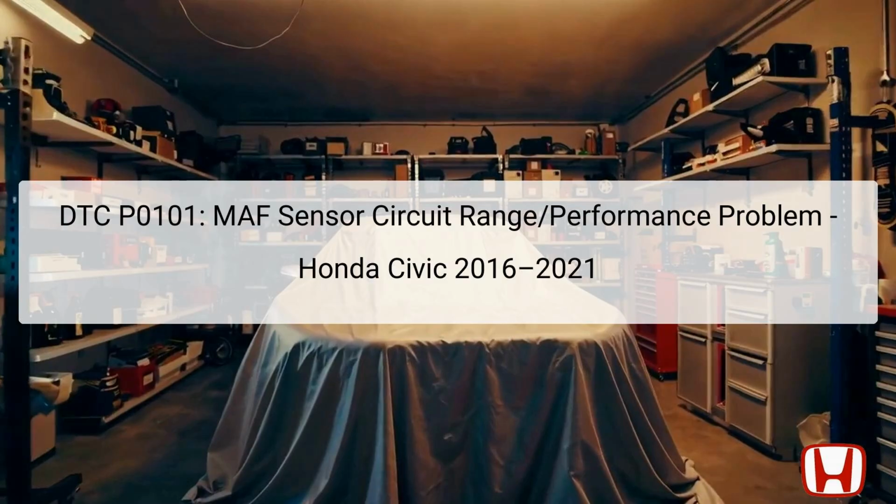Typically located in the intake air duct, this sensor can lead to poor engine responses and increased emissions if not functioning correctly. If this DTC is accompanied by other codes such as P2073, P2074, P2228, or P2229, it's essential to address those first. However, troubleshooting for P0101 will focus specifically on the MAF circuit in relation to its performance.